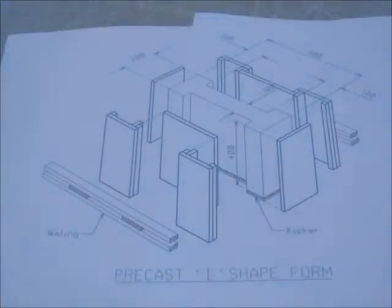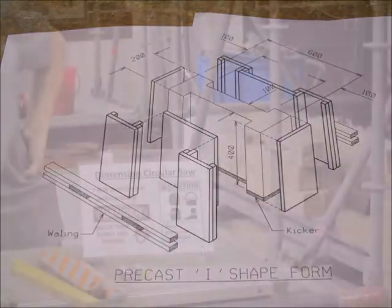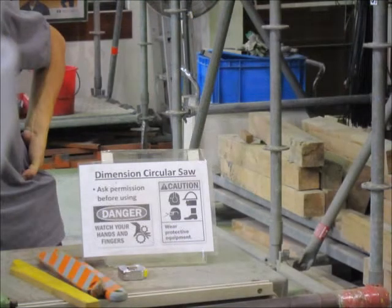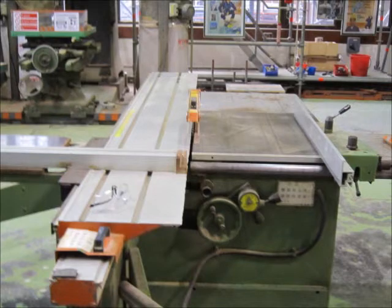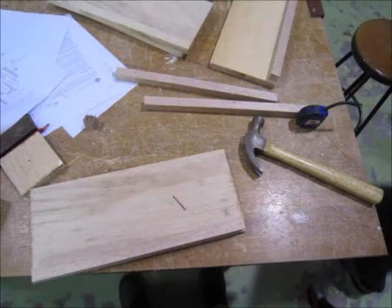In formwork training, we are required to use plywood to make a small-size I-column formwork. We measure the required dimensions of the plywood and use a circular saw to cut the plywood. It is essential to check that the dimensions of the formwork are accurate, because that will affect the appearance and the dimensions of the concrete. Then we use a hammer and connect by nails. Finally, the formwork was erected.